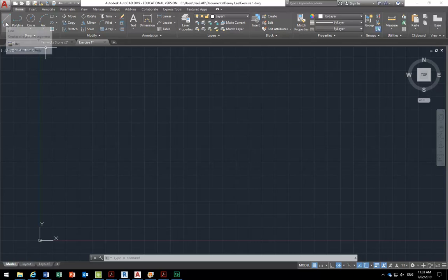So now, again, I'll start drawing my line, clicking on the line button on the home tab. Then you can see these coordinates come up. They're X and Y coordinates. We don't really know where we need to draw for now, so anywhere pretty much will be okay, as long as it's to the right and above that XY origin. I'll click a point up there somewhere, and you can see that it snaps to the angles, and that's because polar tracking is turned on.